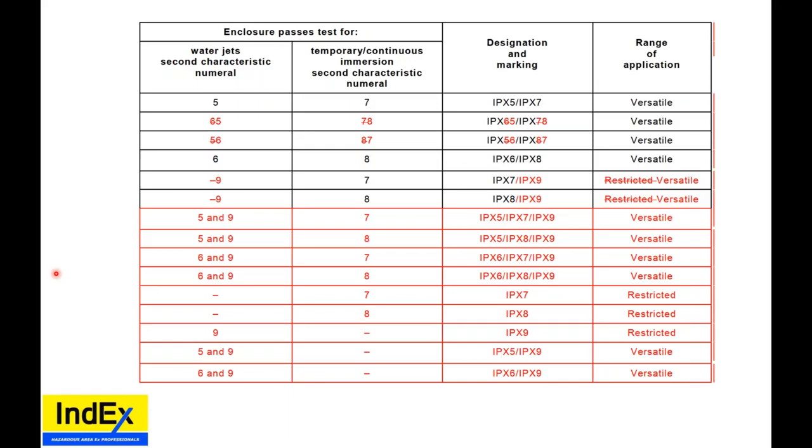While they may produce a data sheet, if it's not on the certificate and it's not on the EX data plate, if one of those documents or physical devices, the data sheet, the data plate, and the brochure, is lacking that information, by my own personal risk assessment, I would not accept it. There are errors within that manufacturer, or perhaps within that certification body or testing laboratory, and I would be apprehensive to accept that equipment. We have found within Australia, a certain manufacturer of LED lights has gone out of business because they did not meet their IP66 rating, and now it's costing end users millions upon millions of dollars to change out all those lights.